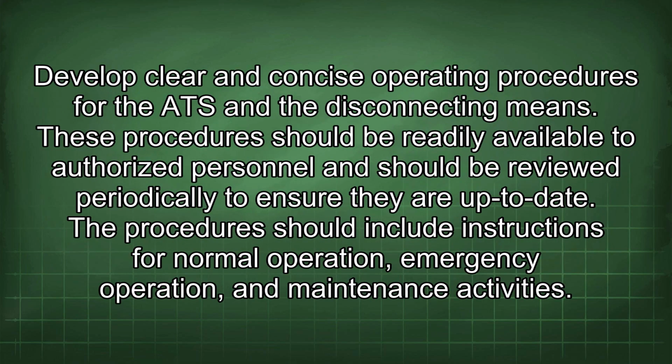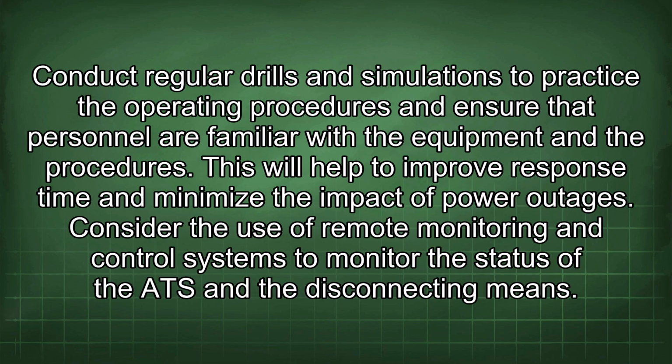Develop clear and concise operating procedures for the ATS and the disconnecting means. These procedures should be readily available to authorized personnel and should be reviewed periodically to ensure they are up to date. The procedures should include instructions for normal operation, emergency operation, and maintenance activities. Conduct regular drills and simulations to practice the operating procedures and ensure that personnel are familiar with the equipment and the procedures. This will help to improve response time and minimize the impact of power outages.